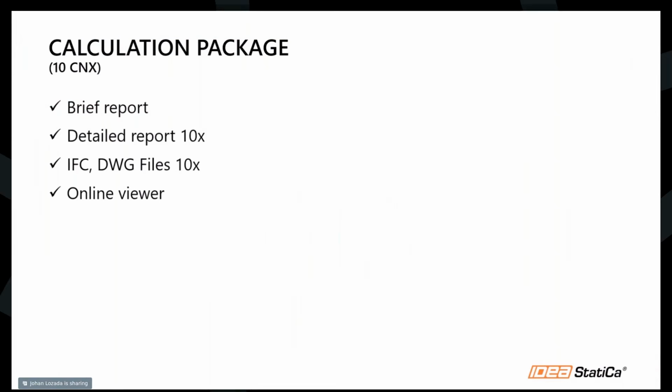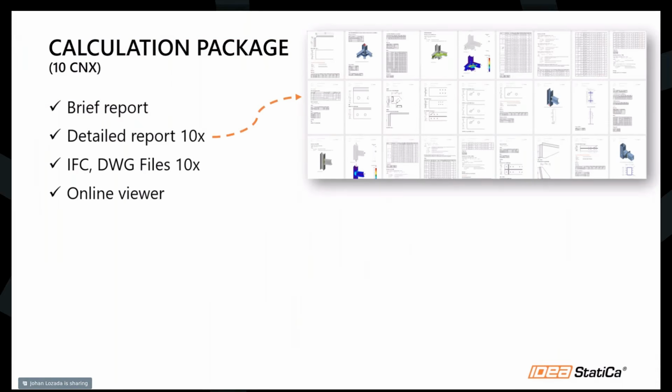The calculation package is as important as the connection design itself, right? So with IDEA StatiCa, you can create this calculation package, including a brief report as we saw it during the demonstration. We can also generate this detailed report from that file containing 10 connections. In this detailed report, you can include pictures of the connection, the view of the stresses on the entire model, drawings. You can also add the tables where the bolts and welds results are included.